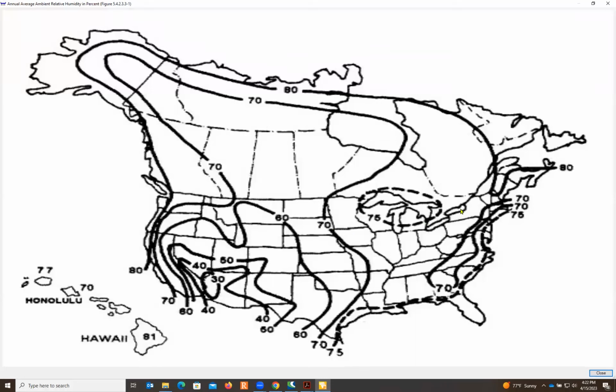And currently we design things right here in this New York region. So the default 75, that is pretty accurate for this location. But if you design something in a dry region, like for example, Colorado, Texas, Arizona, and those, you have to update the humidity in order to get the accurate number for the lump sum pre-stressing loss.